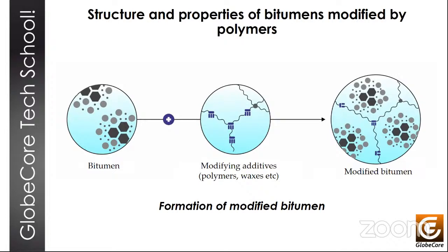Depending on the ratio and chemical structure of the components of the dispersed phase and the dispersion medium, a special structure of asphaltenes in a swollen polymer network is formed above a certain critical concentration of the polymer, what you could call the critical concentration of structure formation. And this structure can be a spatial network of polymer within the coagulation framework of asphaltenes, or a spatial network of asphaltenes and polymer. And these polymer structures impart their mechanical and rheological properties to the original bitumen.